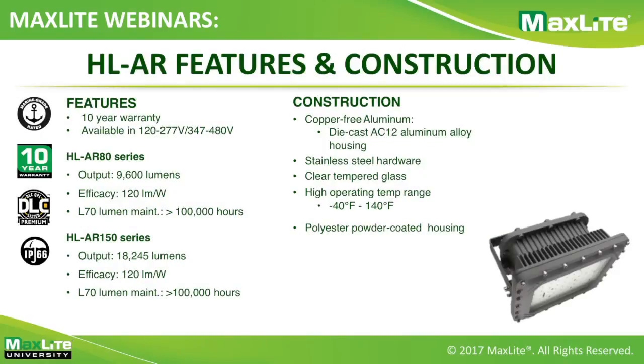One of the many interesting and competitive things about this product is that it also comes with a 10-year warranty for all wattages, along with 120 to 277 and 347 to 480 volt operation. It's DLC Premium qualified for all wattages, it's IP66, and it's our second marine grade rated fixture as well. With lumen maintenance of more than 100,000 hours and a worry-free 10-year warranty, this fixture is a perfect replacement for the most common HID wattages seen out there.